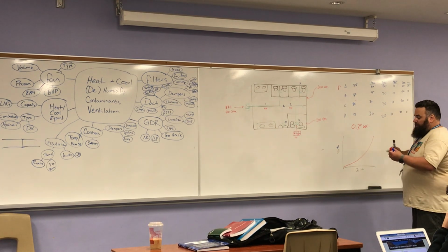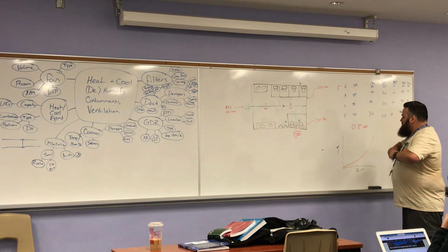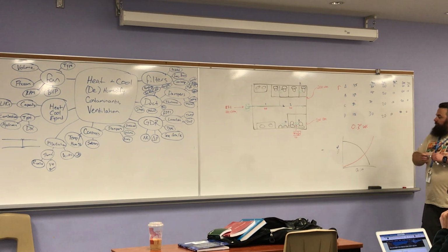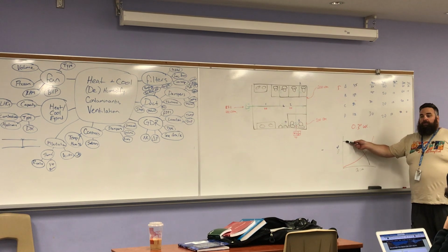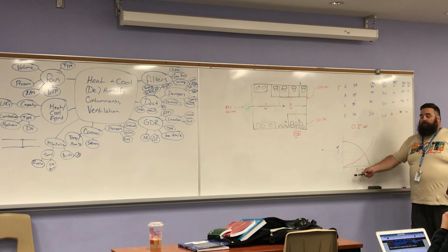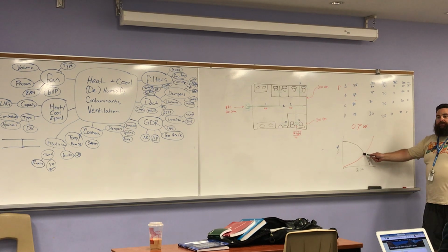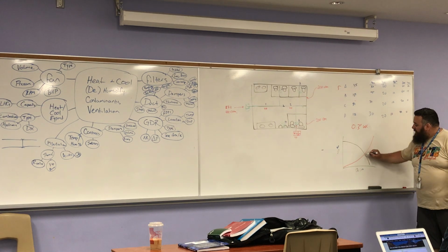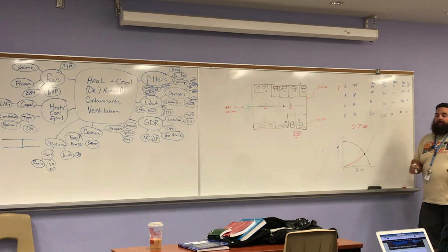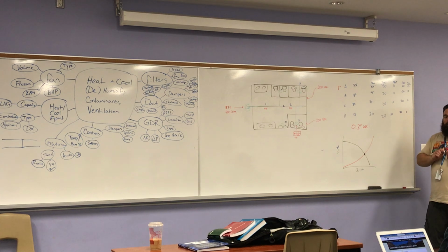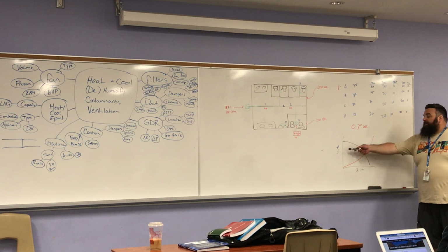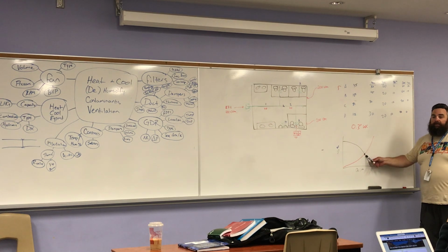pressure does this. The higher the pressure of the fan, or the pressure drop of the fan, the less CFM it moves. As that pressure drop reduces, there's less friction, we can move more air. Where do those two intersect? That's where I want my fan to run. I want enough RPM to achieve that. I need enough brake horsepower to achieve that.